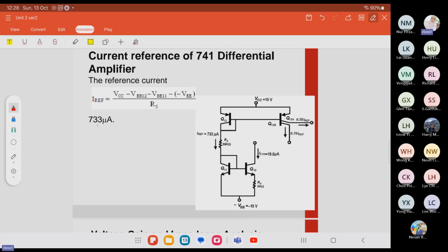It is actually a constant value. For the reference bias current circuit, the bias current IF is generated in the branch composed of two diode-connected transistors Q11 and Q12 and the resistance of R5.